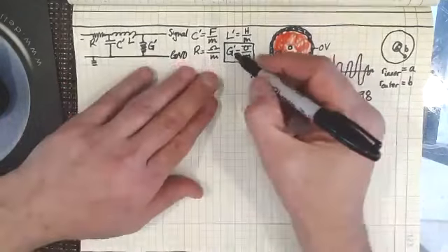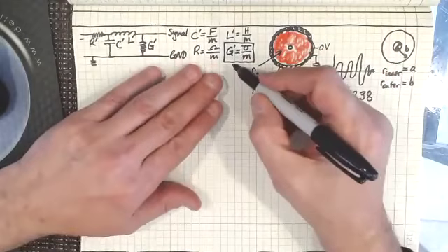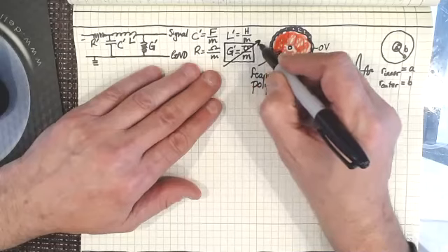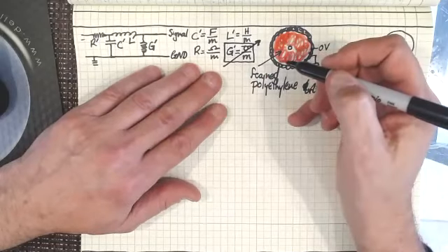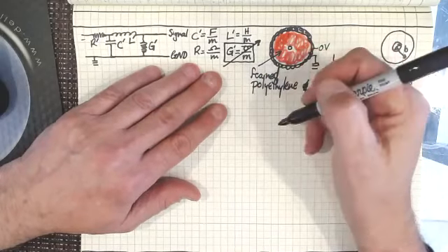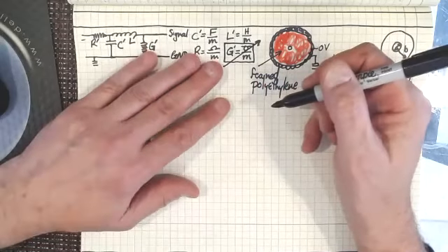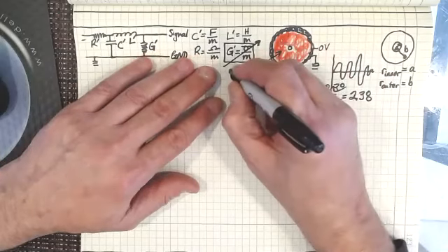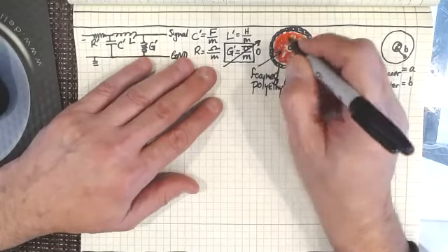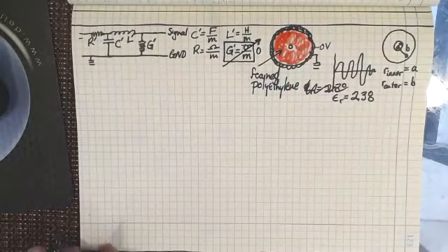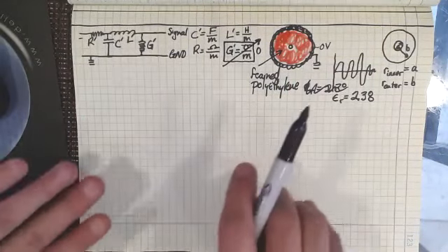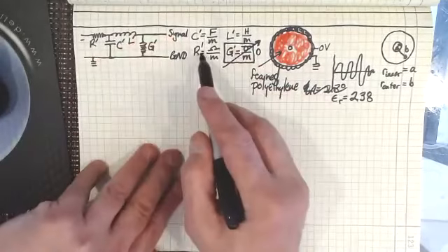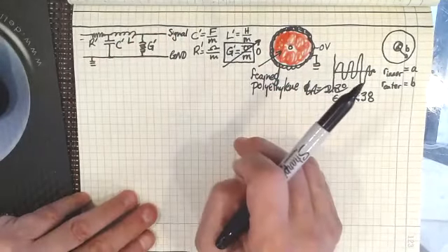But nowadays, and everything that we're going to be doing in this class, with modern metallic conductor technology, G just doesn't exist. Plastics are such good insulators that G we can really say is approximately zero. In fact, negligible, if not zero. Now let's look at the other ones. Let's look at R prime, C prime, and L prime.